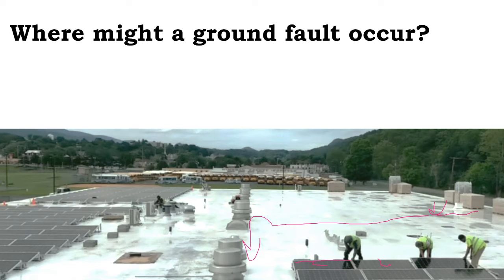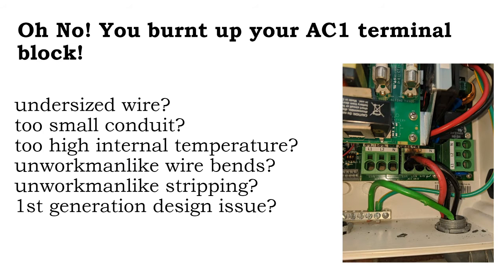A lot of the safety provisions that have been added to solar have been about isolating the power at the module level itself rather than at the array level. Because once you get up to circuit level power, if you're ground faulting on the rooftop, it can be very difficult to actually turn that ground fault off. And there's been fires because of that. The causes of those fires have been addressed in code and design changes in other places, but nonetheless, the code has said, no, we're going to start isolating the power at the array itself.